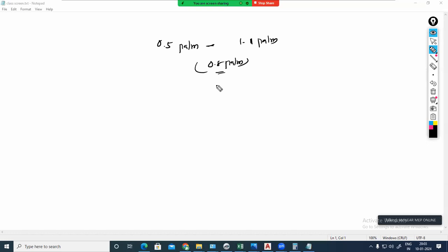for ductable split AC, if the flow rate is high and you are using 0.8 Pascal per meter, sometimes the velocity will come higher than 6 meter per second. In that scenario, instead of 0.8 Pascal per meter, you have to go for less.